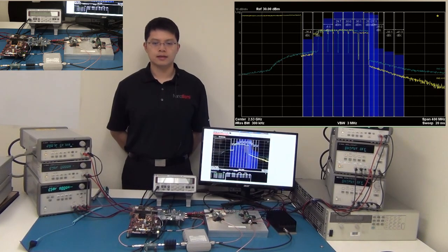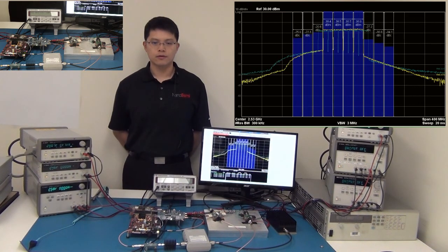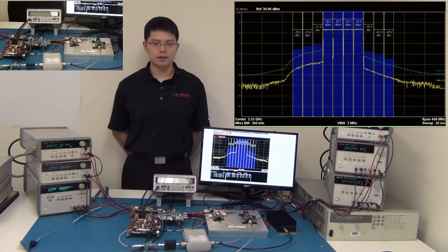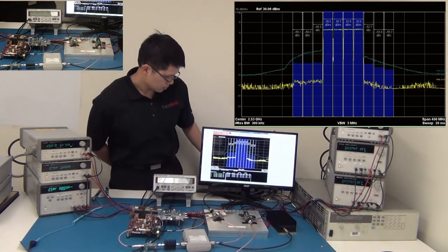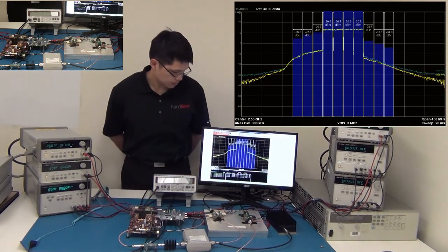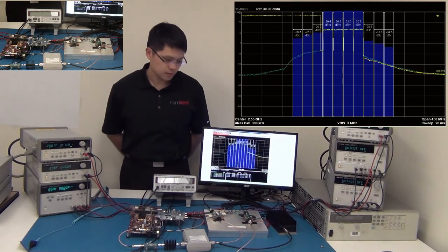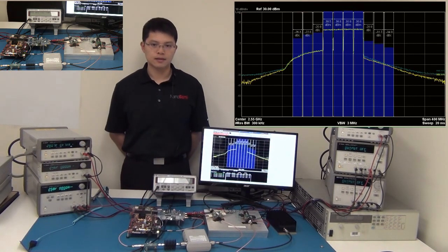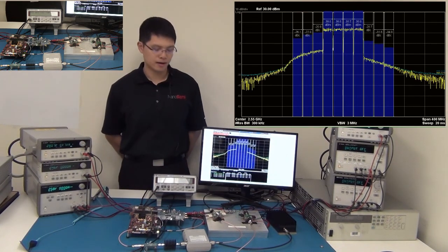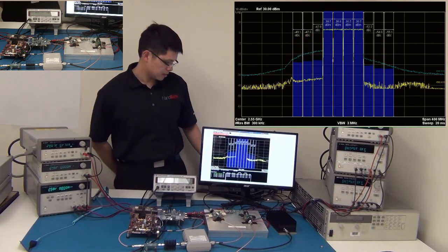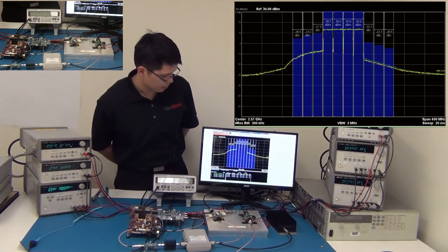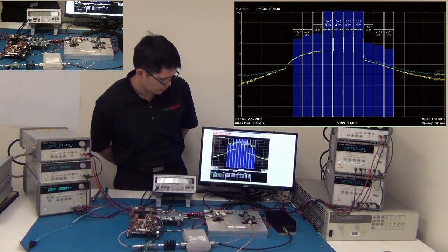The remaining 3 carrier configurations consist of 4 component carriers. Each of them occupies 80 MHz, except that we will park the carrier at different center locations. The next one actually parks at the center frequency of 2550 MHz. Then we will slide this carrier configuration by another 20 MHz, centering at 2570 MHz.